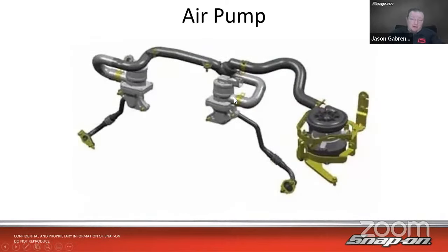Here's an electric air pump setup. This is off a Subaru. So we have the electric air pump. In this case, it's off to the side. And then it has a hose that goes in, splits off because it's horizontally opposed in this, the way the engine's configured. Then we have these 2 solenoid valves, which are variable solenoids. And then they have metal pipes that go down to the back of the exhaust ports on the engine there.